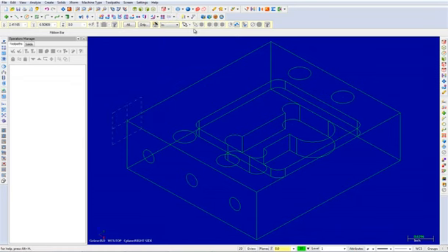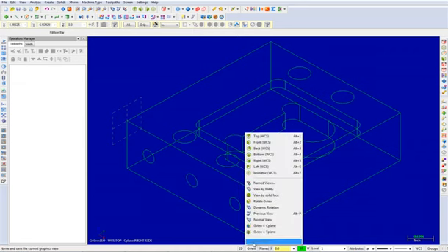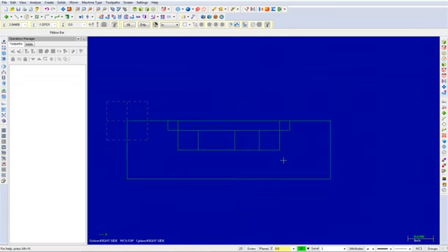This will allow you to create geometry on the right or left side of the part depending on the construction depth. That being said, make sure the construction depth is set to 0. In the status bar, select G-View and choose the right view. This will allow you to view the part from the right side. From here we will create the slot.